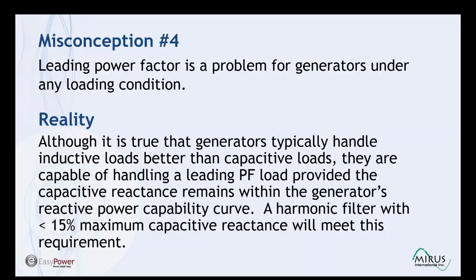So misconception number 4 is that leading power factor is a problem for generators under any loading condition. The reality is, it is true that generators typically handle inductive loads better than capacitive loads. They are capable of handling a leading power factor load provided the capacitive reactance remains within the generator's reactive power capability curve. A harmonic filter with less than 15% maximum capacitive reactance will meet this requirement.